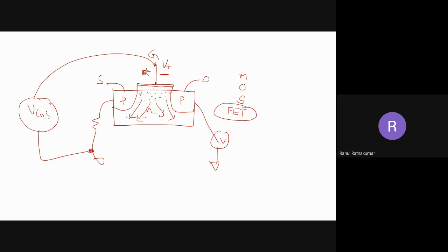Now all the minority carriers, holes, will be coming to the top of the semiconductor just beside the oxide layer. This is the oxide layer, right? So what happens because of the electric field generated through the oxide? There is no current here, but the electric field is very strong. So negative voltage attracts a lot of holes, so this positive carrier, now this junction or the channel is formed, complete channel is formed, resistance is reduced.